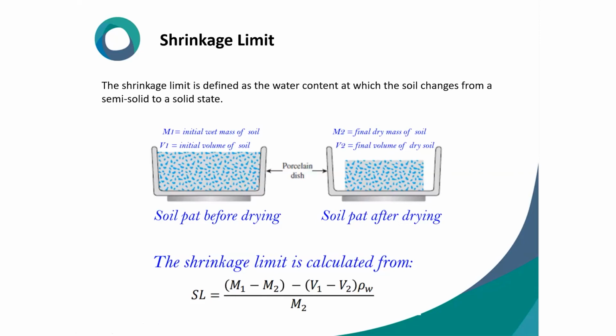And also the shrinkage limit defines the water content at which soil changes from semi-solid to solid state. So this test you will be doing in the laboratory. You will identify the shrinkage limit.